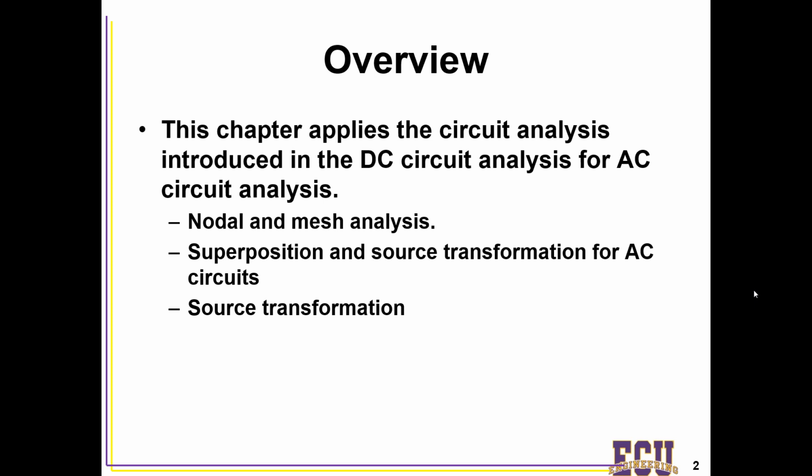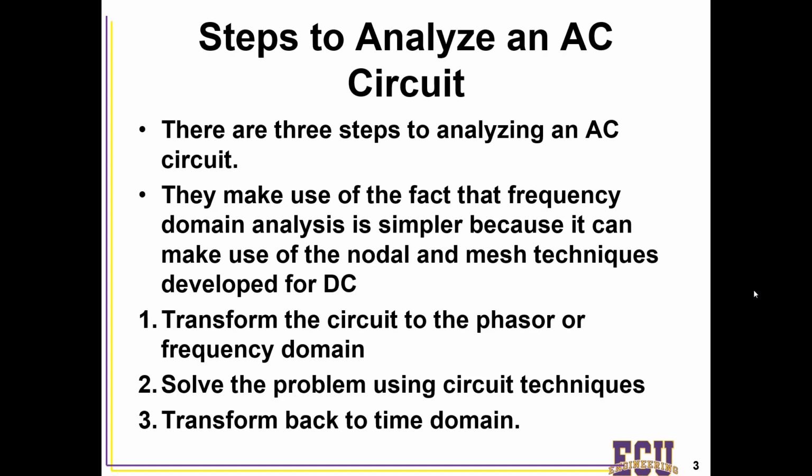The only difference is now in AC, what we're going to be doing is dealing with phasors and with some complex impedance. So let's dig into this right away. So the basic steps to analyze an AC circuit, there's really just three steps that we've got to get into. We need to transform the circuit into the phasor or frequency domain.